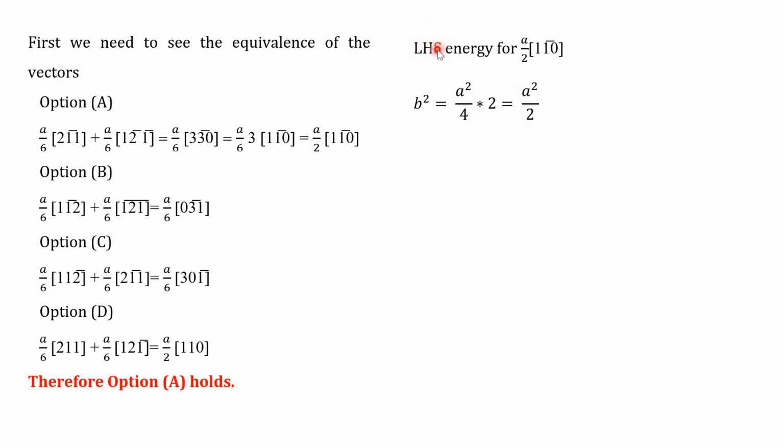So according to the criteria, whenever the dislocation splits into two partial dislocations, whatever energy is associated with the partial dislocations should be less than the energy associated with this term.